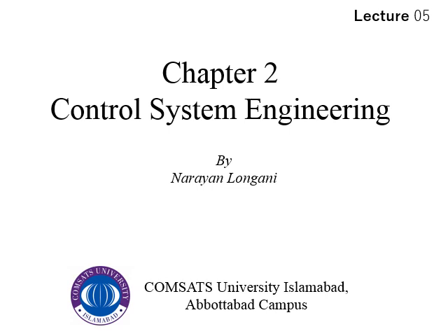And finally, we concluded our last lecture with the topic of impedance for mechanical system, in which we observed the force displacement relation for a spring, viscous damper, and mass, and concluded that impedance for mechanical system is equal to force divided by displacement, or sum of applied forces is a product of sum of impedances multiplied by the linear displacement. This is all about lecture 4.